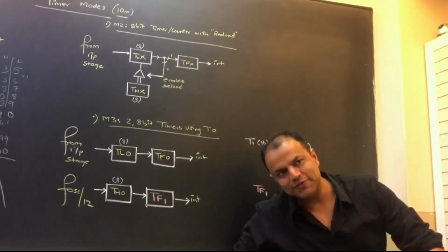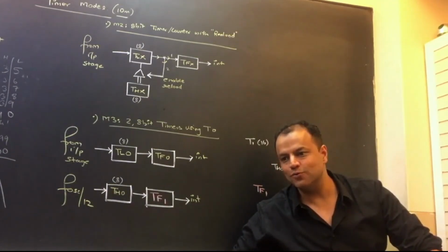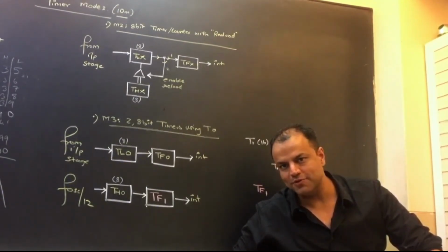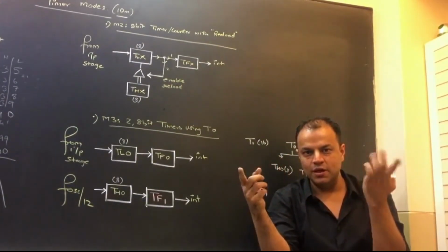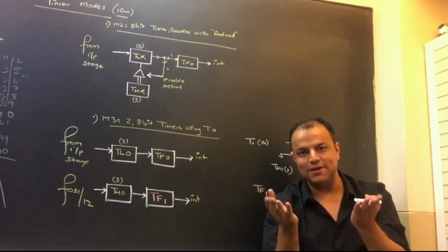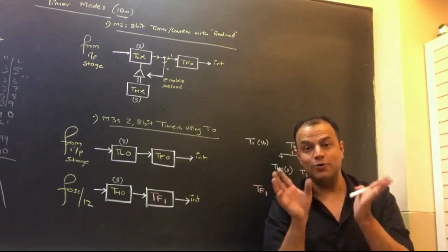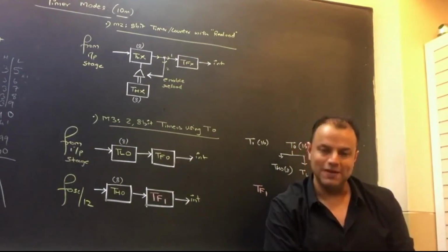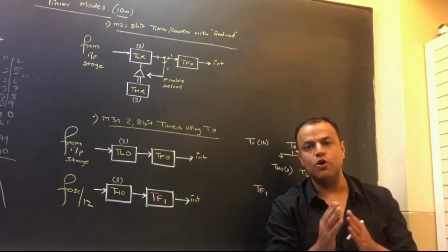That is very obvious. What is going to be reloaded? The count. Random count or original count? The original count. Are we going to give the count? No. The system has to store a backup copy of the count. That means the system has to make 2 copies of the count. One will be used for counting, one will be used for reloading. To make 2 copies of the count, it has to be an 8-bit count, because your whole register is 2 8-bit registers giving you space of 16 bits. If your count itself was 16 bits, both your registers are occupied in holding the count. Where will you store the backup copy? Please tell me, did you understand this? So that is why it's an 8-bit mode, so that you can make 2 copies of your count, one for counting, one for reloading.